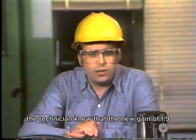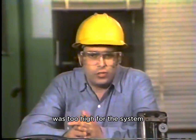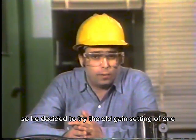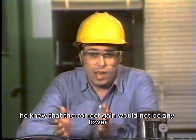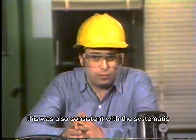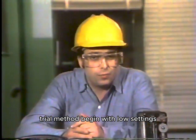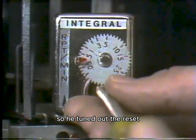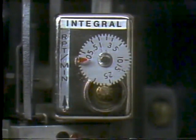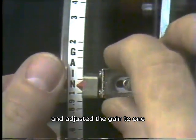At that point, the technician knew that the new gain of 1.9 was too high for the system, so he decided to try the old gain setting of 1. He knew that the correct gain would not be any lower than the old gain. This was also consistent with the systematic trial method: begin with low settings. So he tuned out the reset by turning it to its most minimum value and adjusted the gain to 1.